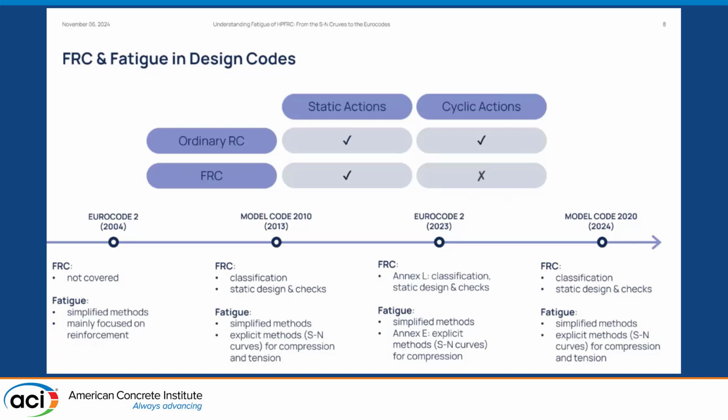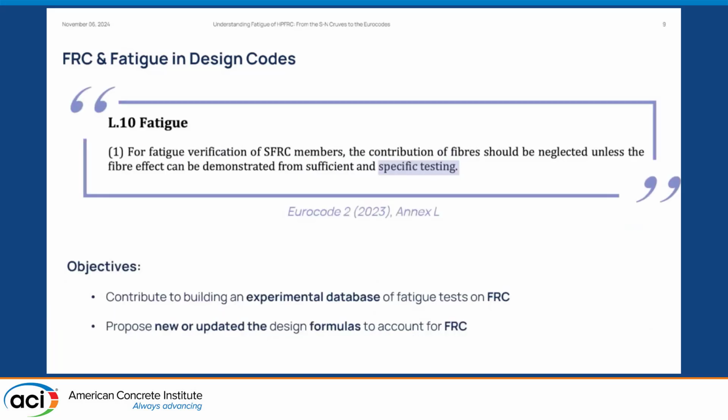So here, just a screenshot from Annex L, which was a great addition, again, to Eurocode 2, covering fiber-reinforced concrete. But probably due to a lack of sufficient experimental testing, there are no specific rules for fatigue on FRC. And the codes actually invite us to run tests. So this is what we started to do.